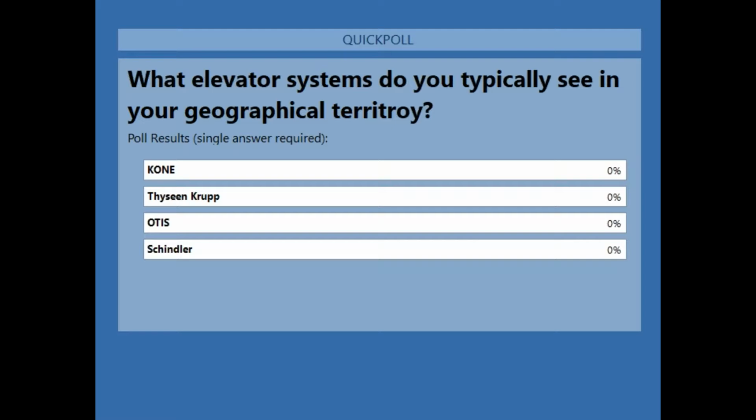The other question that we had here is, is an ACM license required for elevator control? It's not. It's part of ACM. Just make sure that you have enough reader licenses and the necessary hardware, the reader outputs, if you're just doing elevator control. And if you want to do elevator control with floor tracking, in other words, you know what button the person pressed, then you need input points as well.